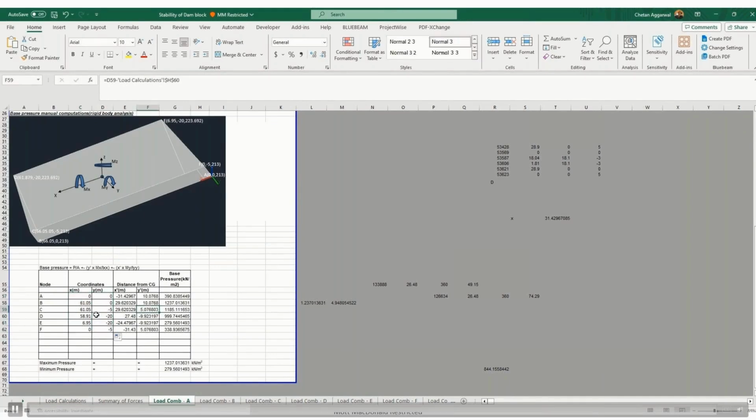So this is now okay. In all other load cases, it is linked with these cells, so this should be fine. I have these load cases with me. We have a maximum base pressure of this much, and if I convert it to MPa, this much MPa. If I consider a factor of safety of 4, we should have an unconfined compressive strength of this much MPa for the rock to bear these pressures, 5 MPa.